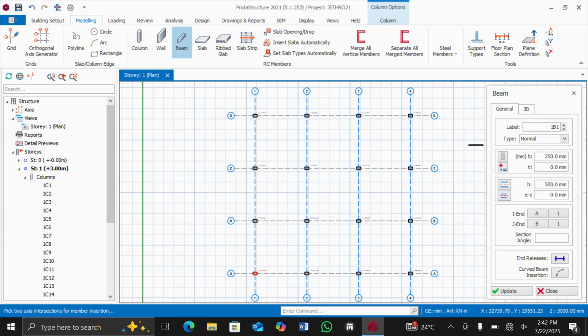Then it is showing you the breadth of the beam to be 250. By the way, this breadth is always taken from the dimension of the wall. So take an example, your wall is 200. If your wall is 200, it means even your beam is recommended to be 200. We need to make beams that are flush with our walls, because creating a beam which protrudes is not interesting, in terms of the breadth.